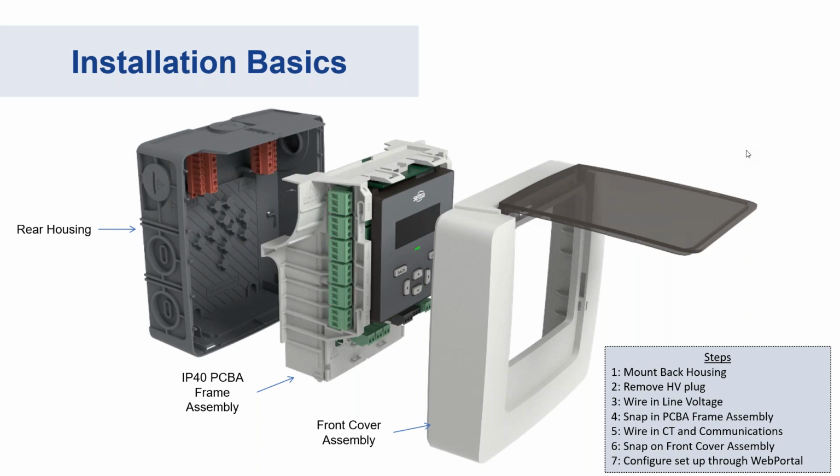Is the trend data stored on the device or in the external software? Mike, I might be able to clarify there, but why don't you go ahead and answer that? Yeah, I think I understand the question. All of the data, 62 days of data at 5-minute intervals, is stored on the meter itself.